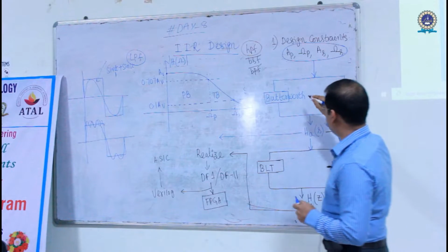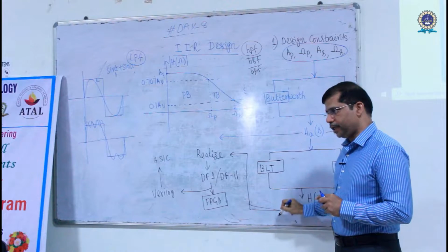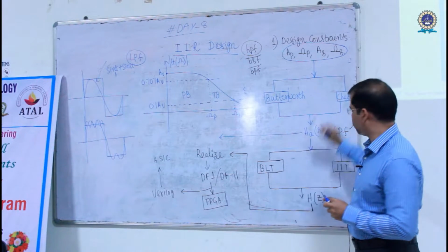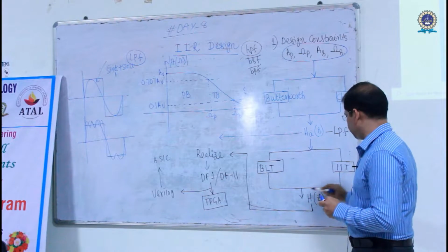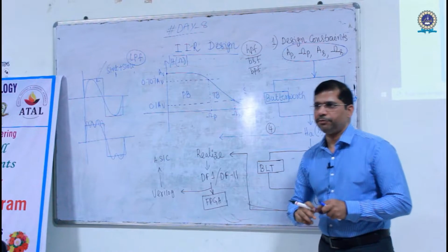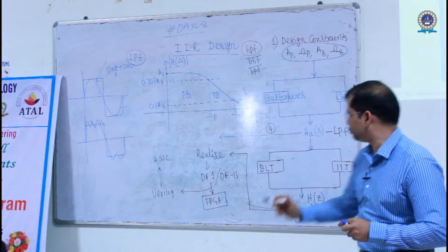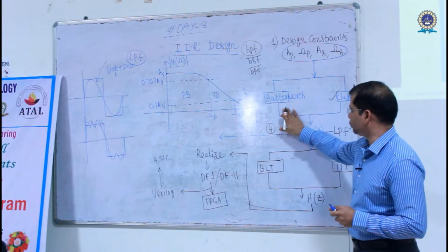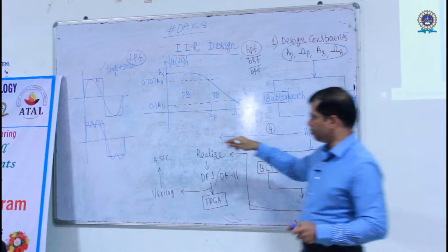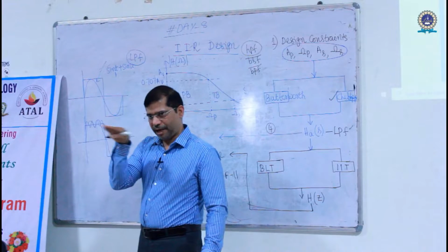Now, if you look at it, either Butterworth bilinear or Butterworth impulse invariant, Chebyshev bilinear and Chebyshev impulse invariant. So therefore we can design this in four ways. Between Butterworth and Chebyshev, Chebyshev is better, because you get more ripples, that is the nice flat approximation you get.